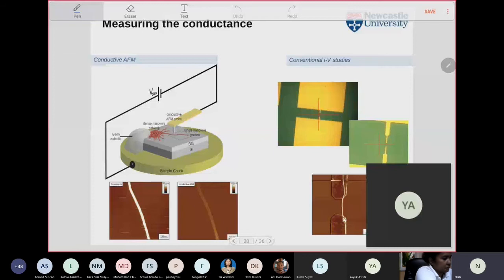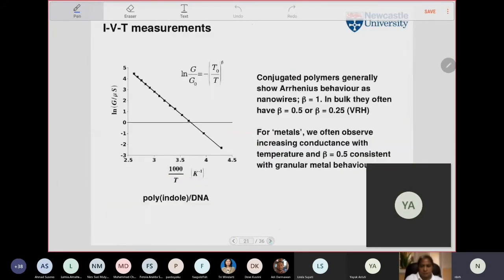But at the edge of that mass, you'll find one or two nanowires which poke out. And you can contact those individual nanowires with the AFM tip, and you can make a second electrical contact to the main mass by hand, just with a toothpick and some eutectic. And so you can actually study individual nanowires by that method. So I'll show you some examples of data.